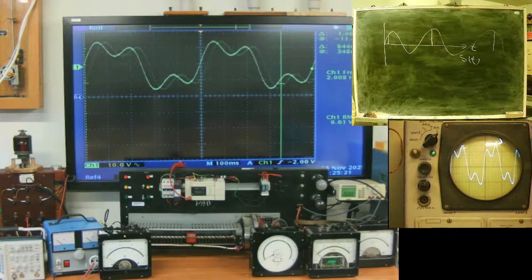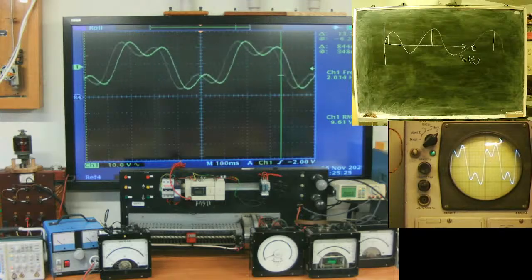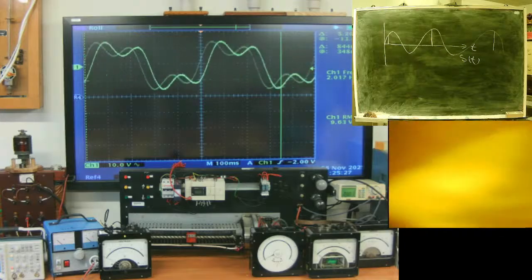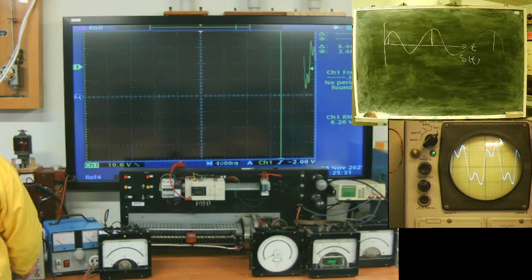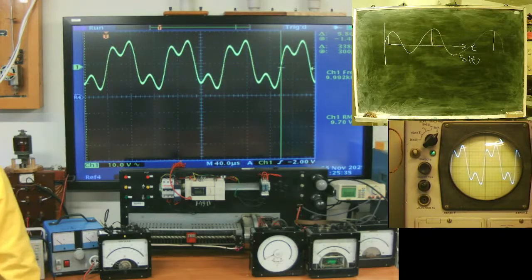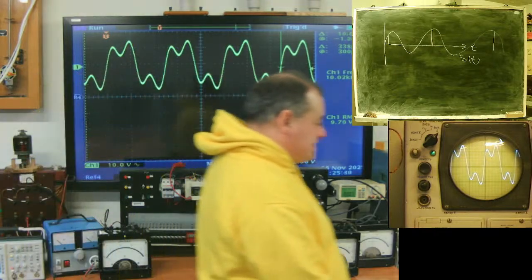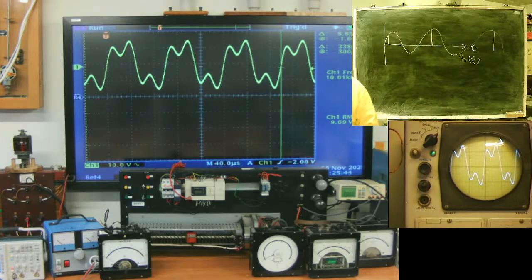We see the effect of aliasing. The sampling frequency is too low. With normal sampling frequency, we should see this 10 kilohertz signal, not a 2 Hz signal with some mirror of it. Here, everything is as it should be.